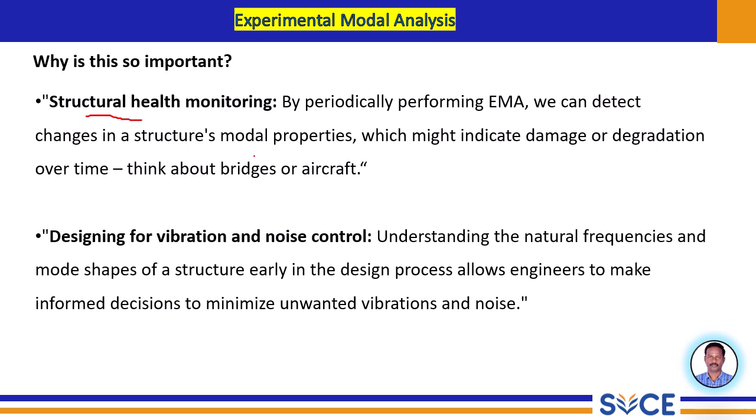By periodically performing EMA and tracking these modal properties over time, we can detect subtle but significant changes that indicate the onset of damage or degradation long before it becomes visually apparent and leads to catastrophic failures.